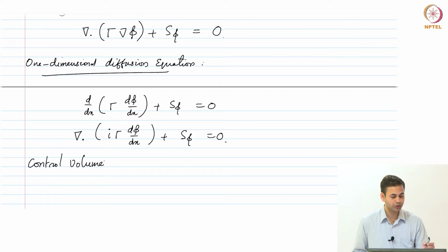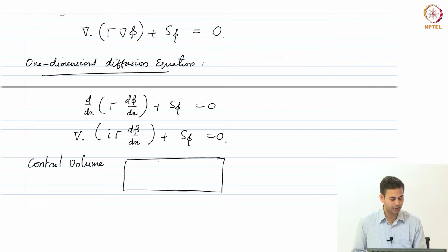Okay, so we are going to discretize the domain, that is, we are going to choose a mesh that looks like this. These are, let's say, the interior cells. We call the primary cell P, and the cell to the east E and to the west W, and the faces of the P cell we call little e and little w.